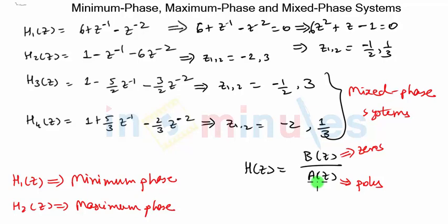For minimum phase, the condition is the same, that zeros must be inside the unit circle. We are adding that poles should also be inside the unit circle because we also want stability apart from the minimum phase characteristic. So the overall definition of minimum phase for our filter is that both zeros and poles must be inside the unit circle.